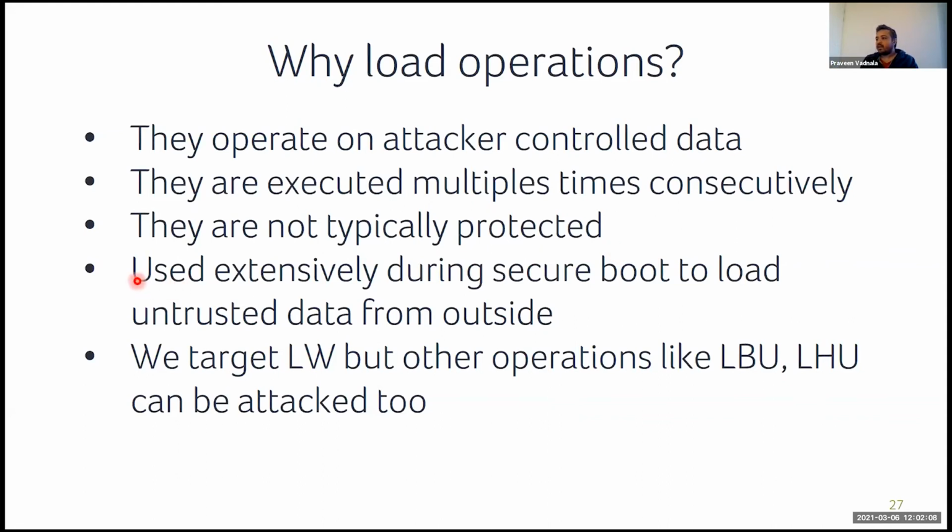And as I also mentioned, there's the use case. In case of secure boot, you load the data from an external flash, for example, into internal RAM. And this involves a lot of loads and stores. So that is why we are interested in injecting faults into load operations.